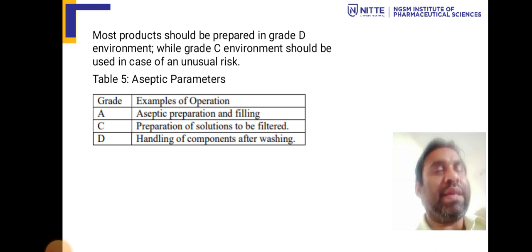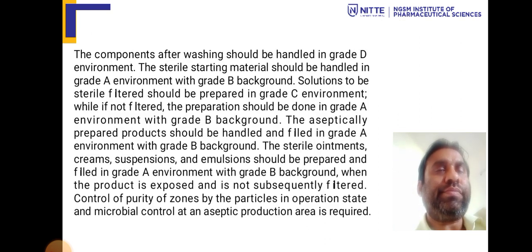Grades are A, B, C, D. Example in grade A, aseptic filling, preparation and filling. In C, we can see preparation of solution to be filtered. In D, handling of components after washing. The components after washing should be handled in grade D environment.